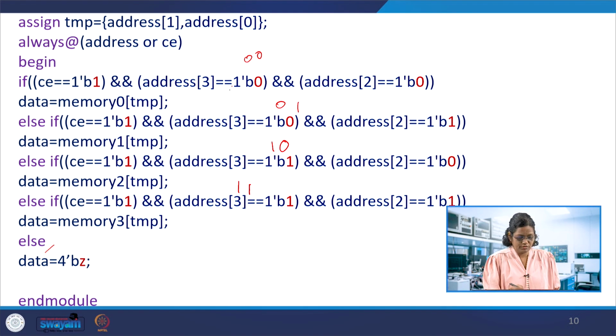Here, if you use this if else statement, it will go for the priority structure. So the priority structure will be realized in the synthesis process. So else data is this, so end. So we have made this if else statement using this always. Now the thing which is necessary to know is this data.